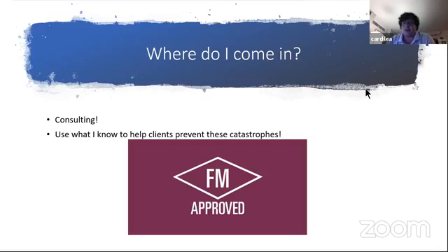Basically, I work for an insurance company, but they have me go into these places often once a year, and I make a series of recommendations based on what I see, and this is part of my evaluation. If I see a situation where there's dust everywhere, I'll make a recommendation saying improve housekeeping. And if I don't think they can improve housekeeping to the point where they can keep their dust hazard under control, then I'll recommend they get collection. If they're collecting inside, the recommendation will be to put the collector outside, something like that. I try to make practical recommendations to help companies not have losses.